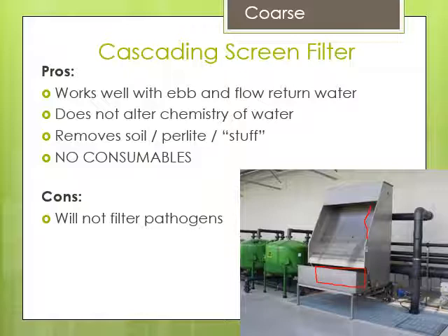It leaks through the screen and comes out the back side. So I kind of misled you there when I first described it. And all the debris, the perlite and the peat moss and the care tags, they slide down the front and end up in the front bucket, this part here. And that's how it mechanically separates debris from the water.